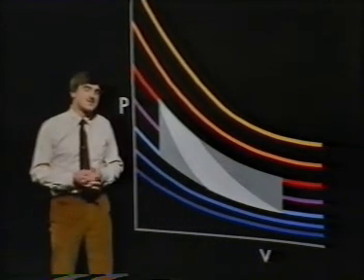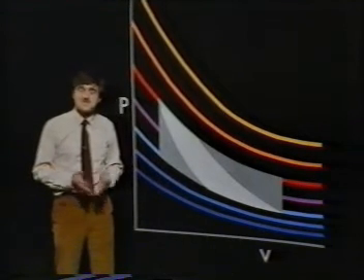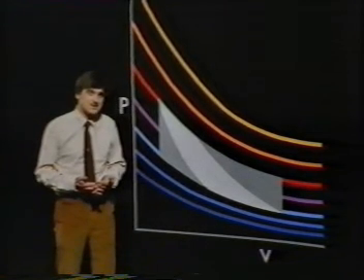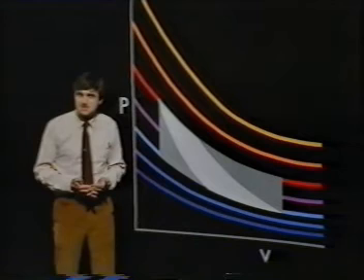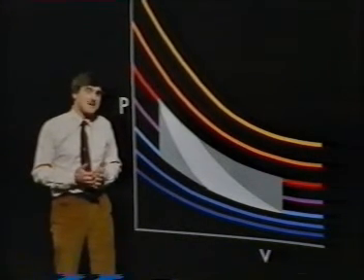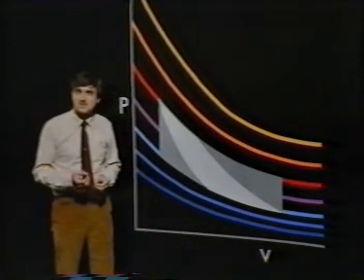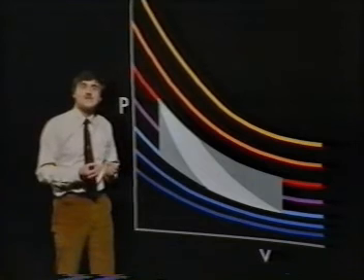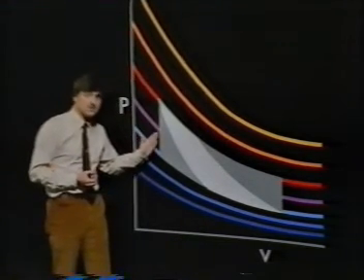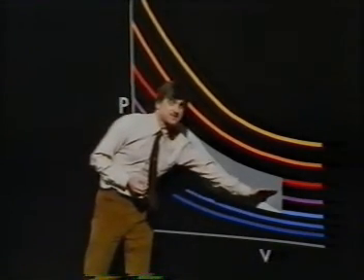Nevertheless, the Stirling cycle is worth looking at further from a practical standpoint. As I said earlier, no one has yet built a true Carnot engine. But Stirling engines have been built, and with thermal efficiencies closely approaching the maximum thermal efficiency of a Carnot engine. And this is done by incorporating an internal heat regenerator, which exchanges the heat from one constant volume process to the other in the Stirling cycle.